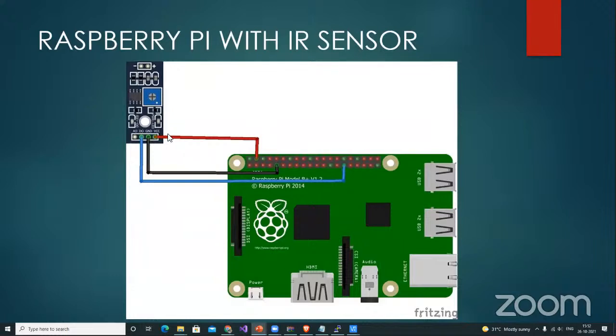Here you can see, guys, I'm using the VCC pin. For powering this module, it's always recommended to use the 3.3 volt pin rather than 5 volt, because it has some potential to damage a particular pin in the chip. Then the whole 4,000 or 5,000 rupees you have spent will go in vain. So remember to provide 3.3 volts. 5 volt is not a problem for a shorter duration, but for the longer duration you have to provide 3.3 volt.